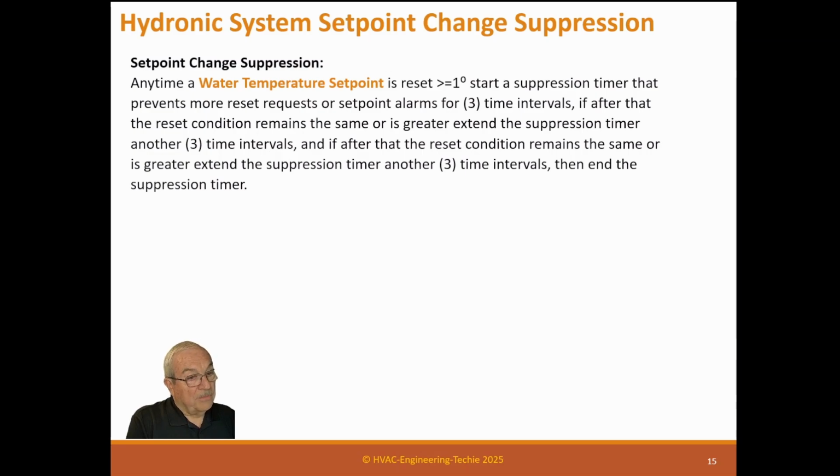You had a set point change, but nothing actually happened. So now the resets get larger, and the alarm persists. So then it asks for more, and then waits 3 more intervals. It doesn't work, so it's going to ask for more. What happens is it keeps asking more and more requests, but the system's not responding.